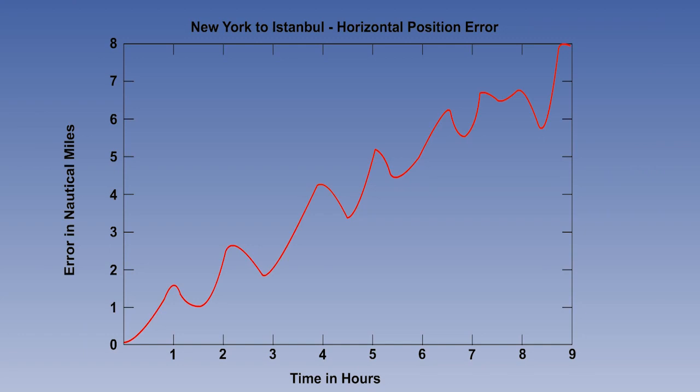Unlike our earlier diagrams, which were idealized, this is an actual plot of INS against GPS on a test flight. The pattern can be clearly seen. There is a basic ramp increasing at approximately 1 nautical mile per hour, with a 1-mile Schuler oscillation superimposed on it.